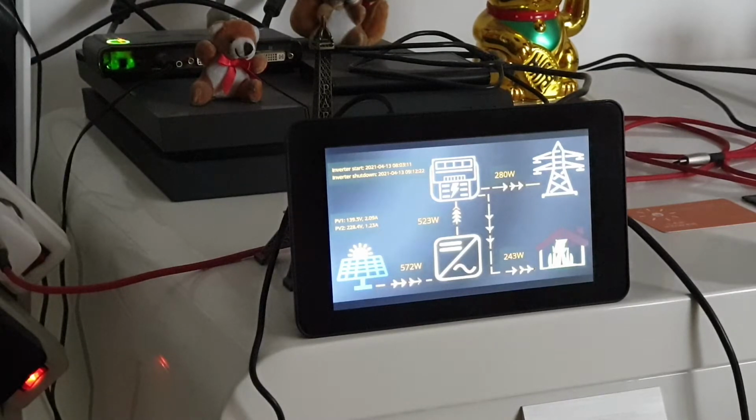And also, that device doesn't need the cloud at all. Other vendors' solutions need some cloud services. I know it's cheaper, but the way that device works, it's more reliable, because you don't even need an internet connection in the place where you have your photovoltaic installation, and you can use it. And for that, I also needed to add an RTC clock module to the Raspberry Pi, because Raspberry Pi 4 lacks that module by default. I will also show you that in a moment.